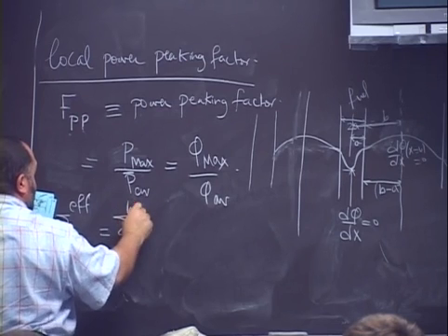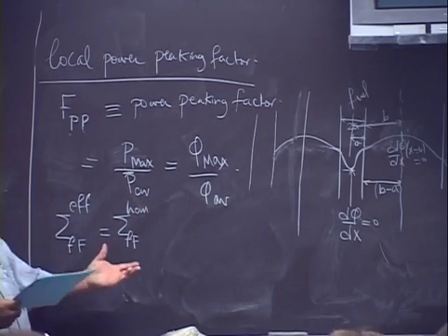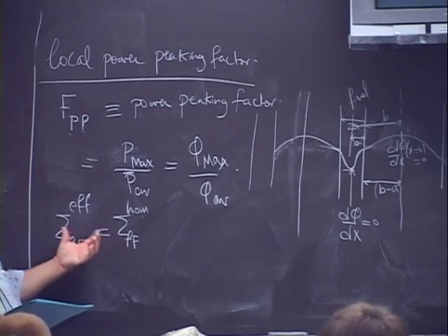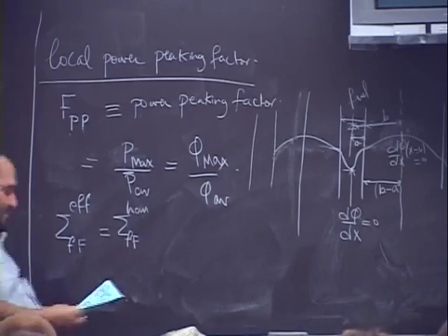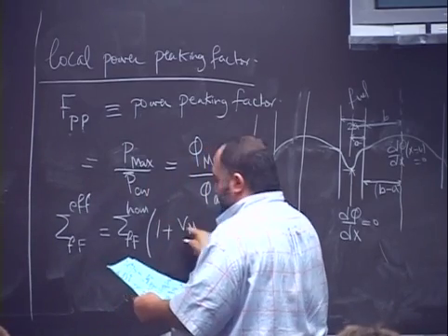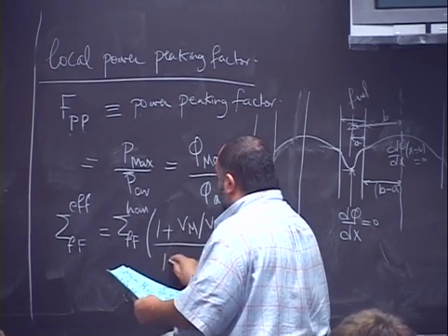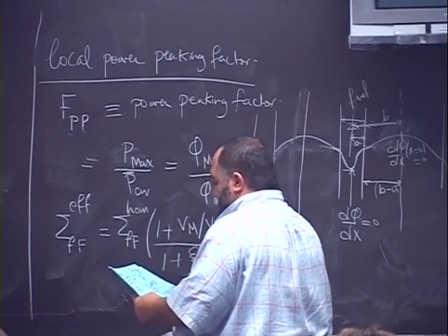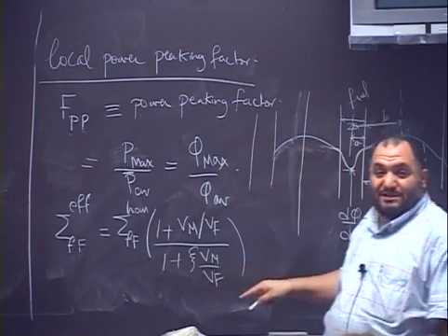In the case of the homogeneous case, again, when we do the homogenization, we notice that we have what? The heterogeneous part is equal to what? Homogeneous part multiplied by what? Multiplied by this factor from last lecture, Vm divided by Vf divided by 1 plus Xa multiplied by Vm divided by Vf. Do you remember this when we made it last time?